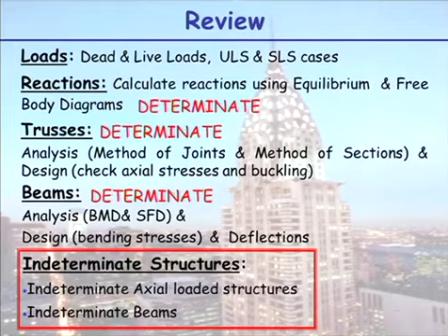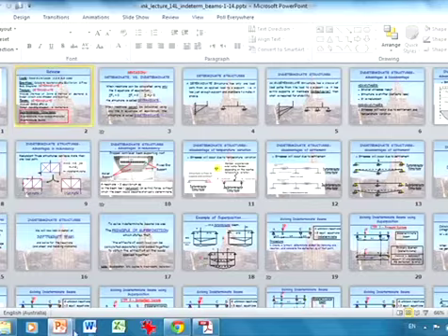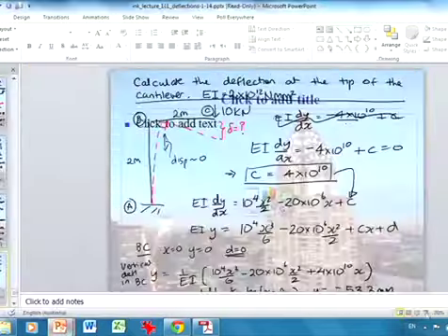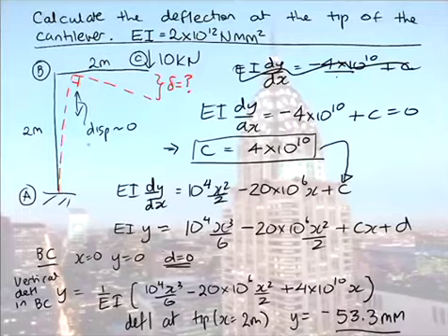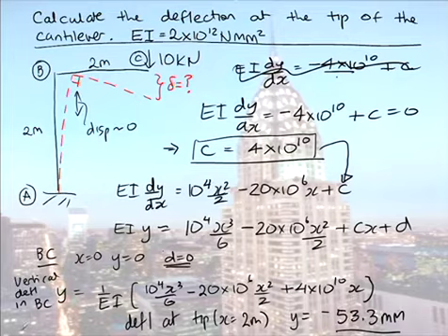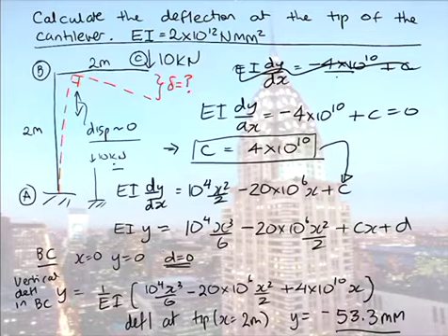No, the vertical displacement is minor. Someone's asking me, isn't there some displacement here? You're asking why is that displacement value there 0? The only reason you'd have a shortening here is because you have 10 kilonewtons acting in your column, and the shortening here, I don't know if you remember the formula yet, will be PL on AE. Remember we did the formula for how much something will shorten or lengthen?